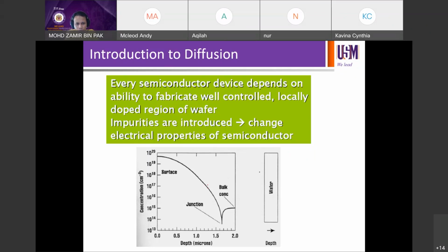Okay, so this is the profile of your dopant, and x0 here is the surface of the wafer, if you like. Okay, x0 is there, and then the profile is going into the silicon. So I have to flip silicon now. So the bulk concentration here is the background doping of the silicon, right? So from the Czochralski process, for example. So in this case, the wafer doping is 10^15.